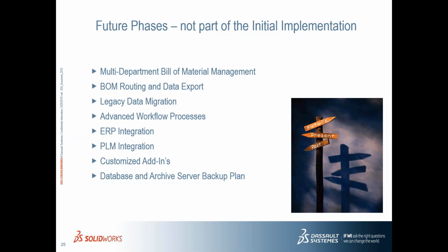One key thing that a lot of people always ask about is their legacy data. They say, all right, Roland, I've been using SOLIDWORKS for 10 years. I got 10 years of data. How do I put that in PDM? The good news is PDM is built on Windows Explorer. So if you trust your data and you say it's good, it's just a cut and paste. You can literally copy and paste it from your current server into PDM and start leveraging the PDM tools.